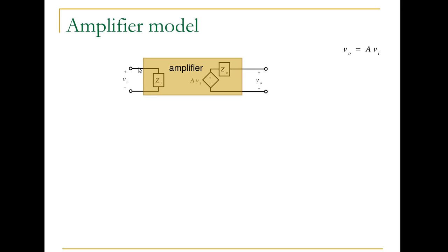And if we have a high input impedance, then the input voltage won't change really. So if there's a low input impedance, there'll be appreciable current going through here, and we will have a different voltage drop across the input terminals than we would otherwise. So high input impedance acts like an open circuit, and low output impedance would mean that there would be a negligible voltage drop across the output impedance. So VO would be what we would expect.